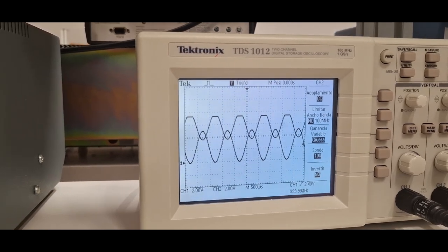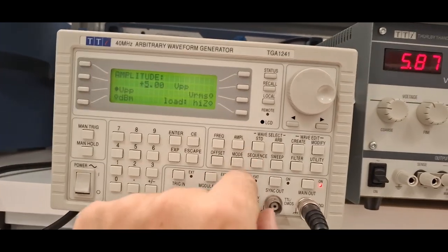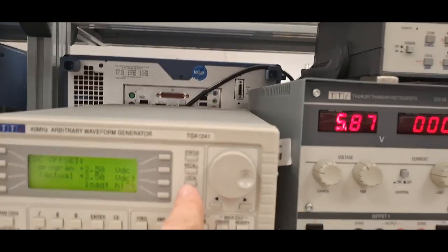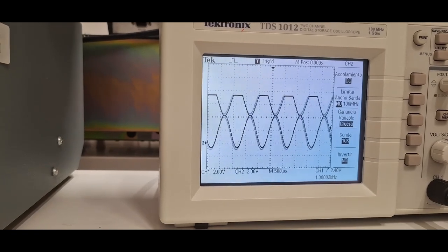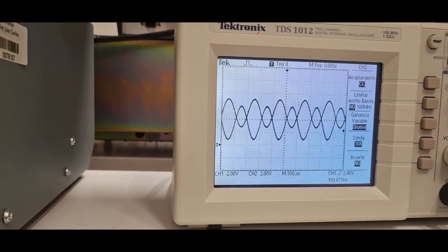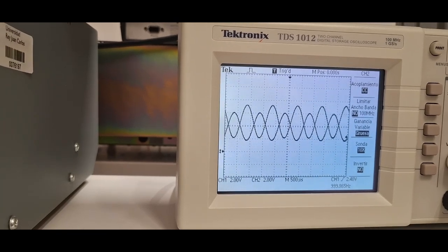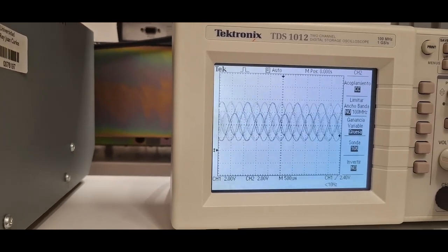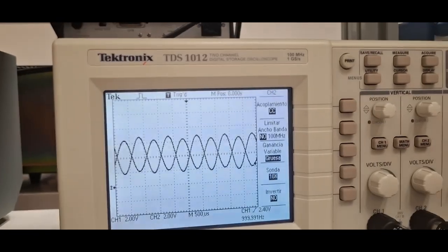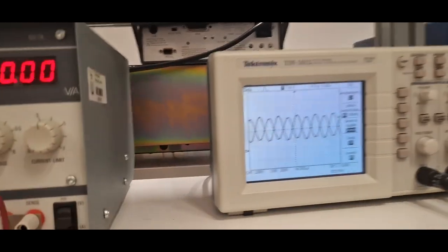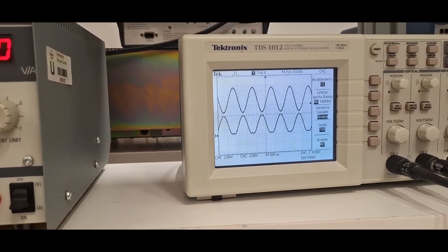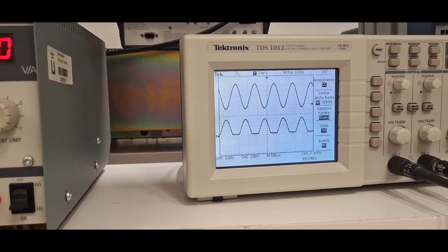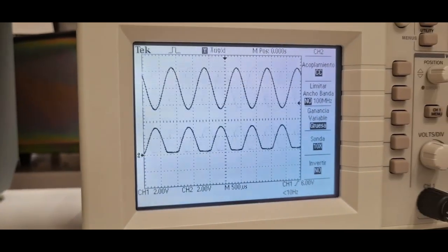We'll see this also. And on the same argument, if I change my offset, so if I move my bias of the input, I will have some clipping of the output signal. I will lose my trigger maybe, yes, exactly. So I will move this a little bit up, and again, if I'm moving, I will finally have to clip, like now, exactly, I'm clipping my output signal.